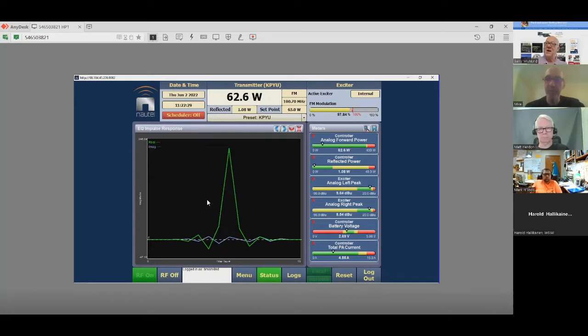Is this a normal looking one? That is, yeah. That's a transient response. If you hit the filter with a step function, it's going to jump up in value and then have some kind of ring to it, based on its Q and some of the other factors. So that's what you're seeing there, that impulse response.